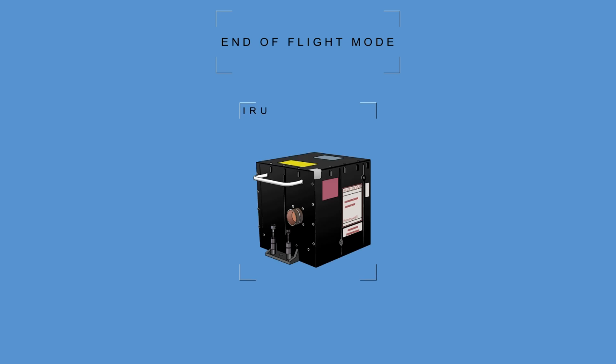End of flight mode. This mode is performed in conjunction with the navigation mode. The micro IRU automatically enters this mode after landing when the airplane has been motionless for a period of 5 seconds. The end of flight mode stores navigation performance records, auto-calibration data, and other miscellaneous information after each flight. IRS operation.